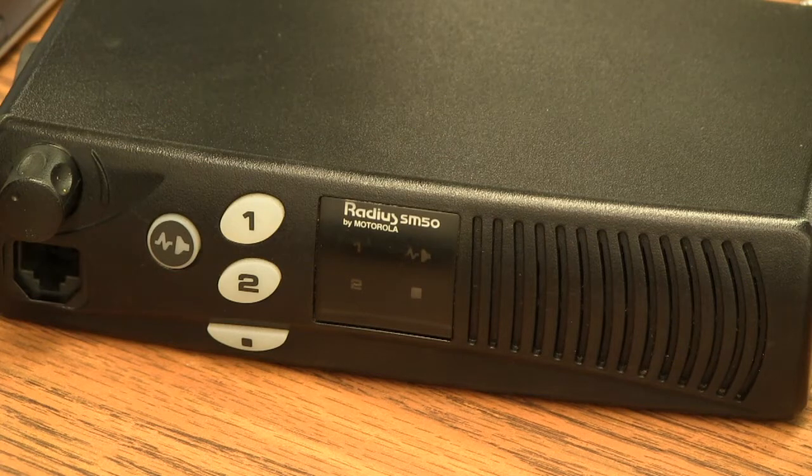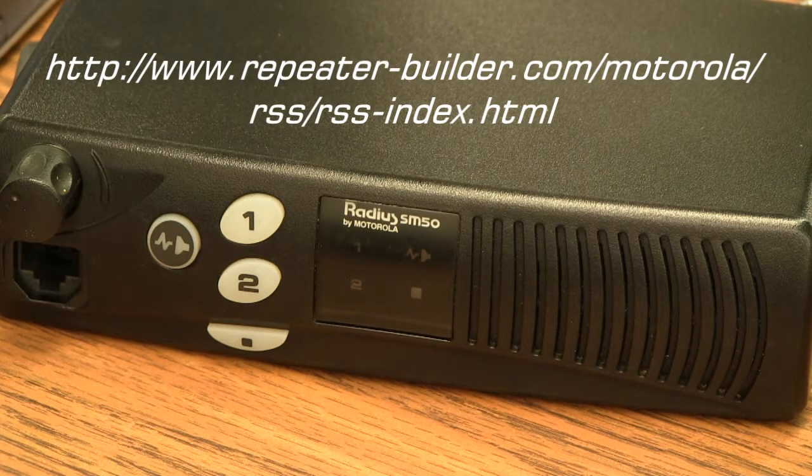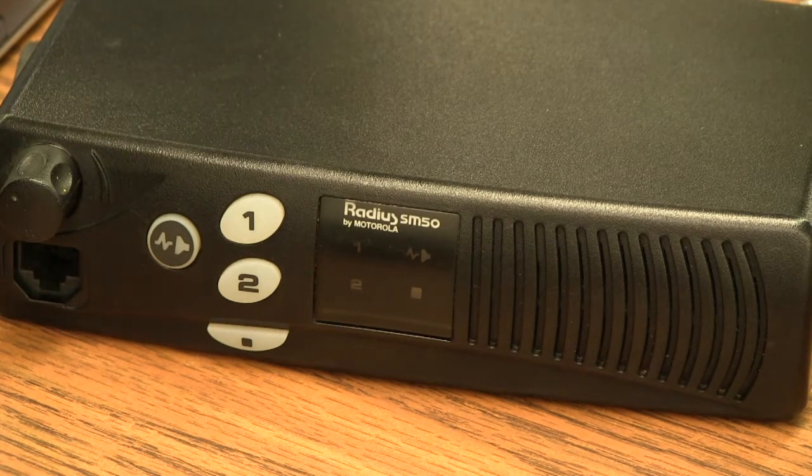Now anyone who's ever programmed a Motorola Radius line radio probably is aware of the trick of holding the shift key down as you input that out-of-band frequency into the computer, lifting the shift key at the decimal point, and then repressing the shift key to finish out the rest of the frequency.